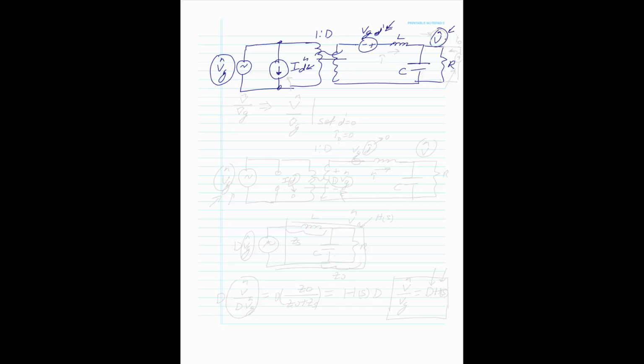And let me add one more thing. We're also going to add an output pulse, and that's going to be I-O hat, the output current being injected in, not the I hat that goes through the inductor here. If we inject this into here, that also is going to move the output voltage, the AC. So it's a small signal injection of current to the output to see the response.